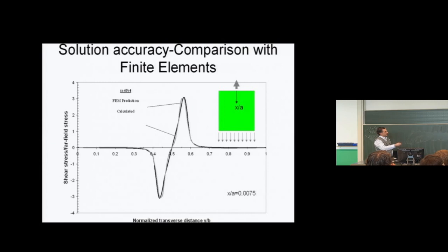Then you would need to reinforce the center. The question is, though, how far on either side of the center should that reinforcement go? As far as the tau xy stress is concerned, you don't need to go any further to the left of this point 0.3 here or to the right of this point 0.7 because the stress there is 0. So now we're starting to not only get a good feeling the solution is good because it matches the finite elements, but also to get a good feeling for what kind of reinforcement we will need.